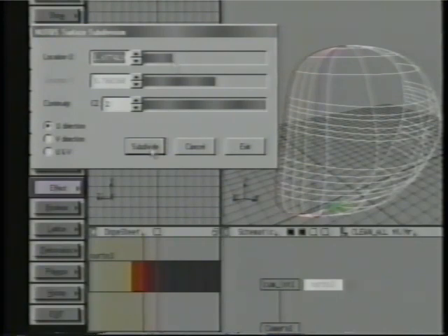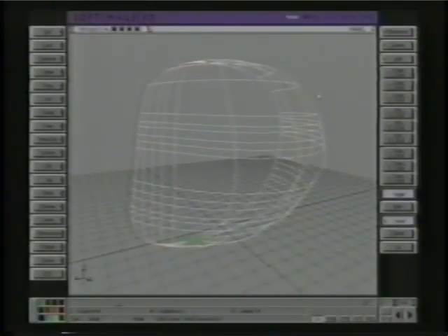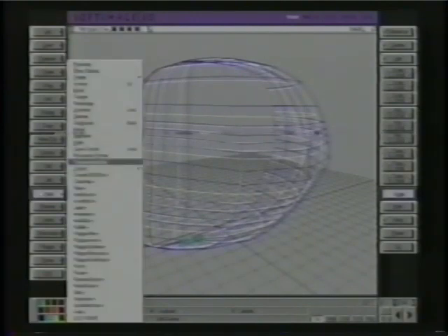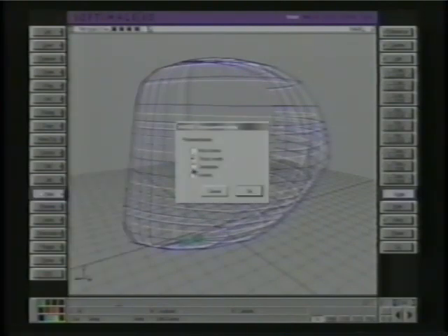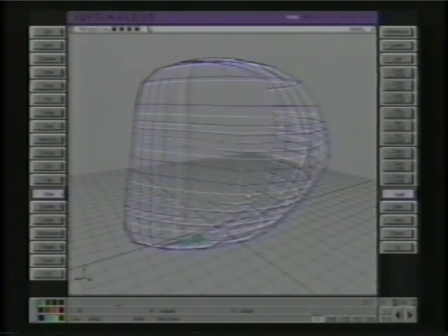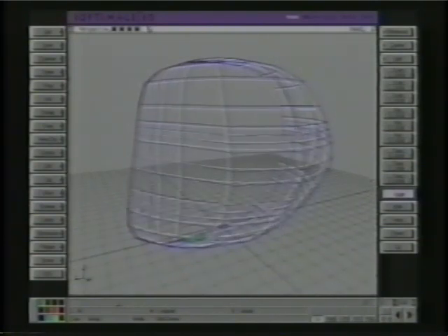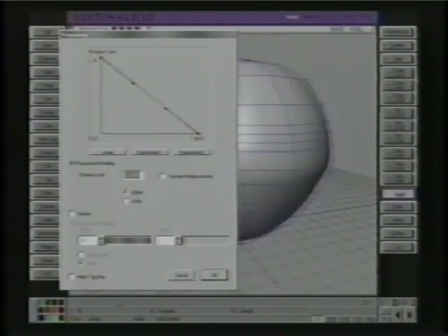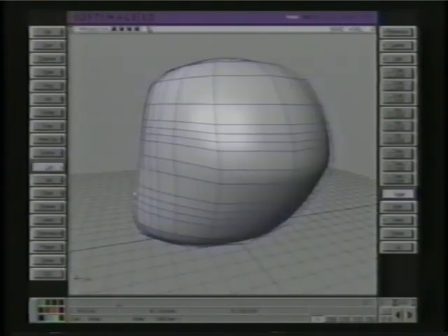Once you've established the overall shape, then you want to start adding localized detail like this. Now in full screen, I'm going to turn on the lines, and I'm also going to do effect reparameterization. We'll talk about this a little bit more later, but I'll switch to chord length, and that'll help the knots on the surface match up a little bit better with the lines that we had. Let's switch to proportional modeling. I'll go a little bit smaller here to 0.5 on the proportional modeling.